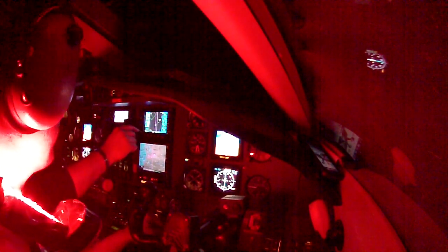113.60. Show me how I find direction to dryer, VOR. 113.6, that's VOR. Yep. Up, up, up. Watch, that's radio. Go to nav, push that button here, and then excellent. And what do you select, nav or ADF? Nav. Nav. Now both on nav.